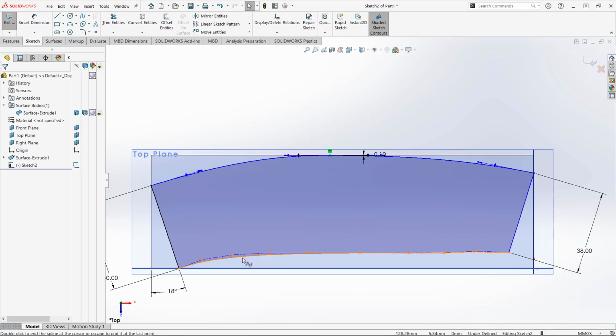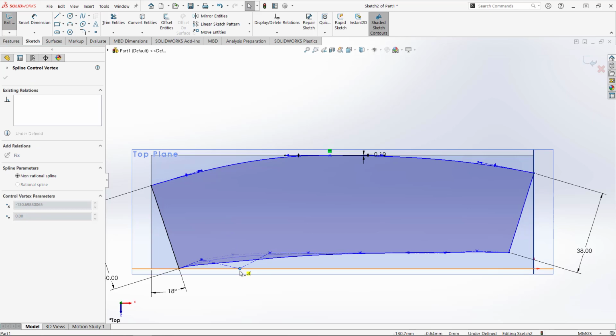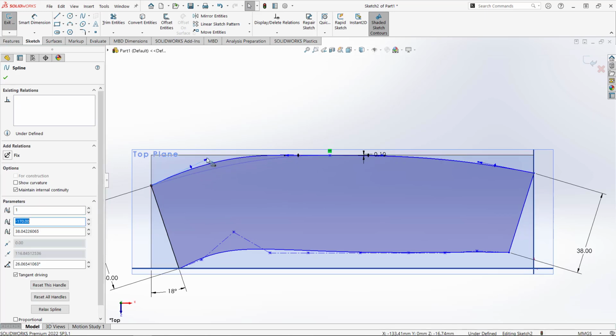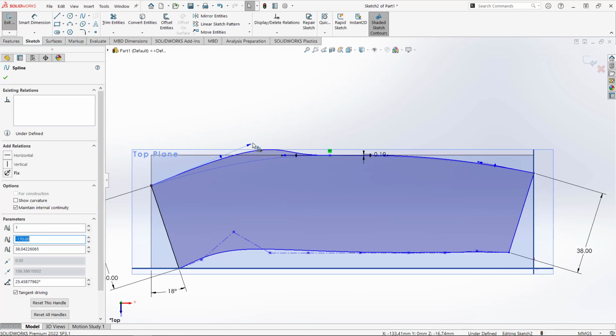And then before I edit this spline, I just want to appreciate the differences between how we work with this type of spline and the original type up at the top. So the original type has these drag handles. They affect the quantity of influence of that particular spline point, and they affect its angle as well.